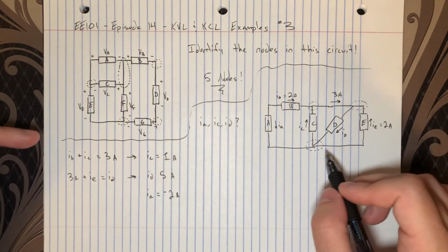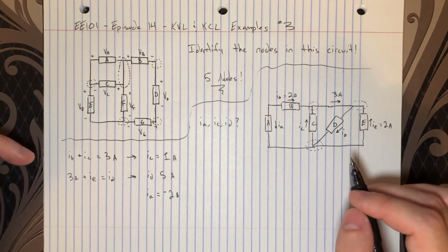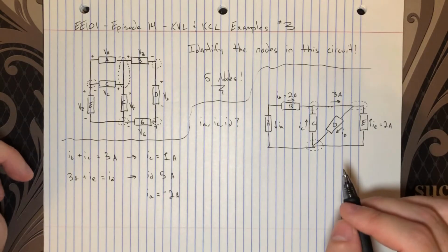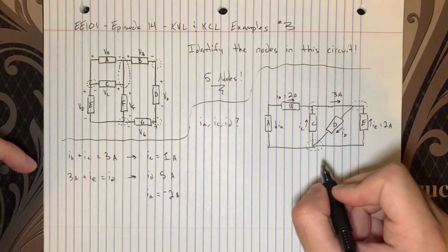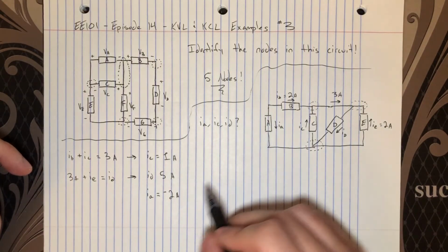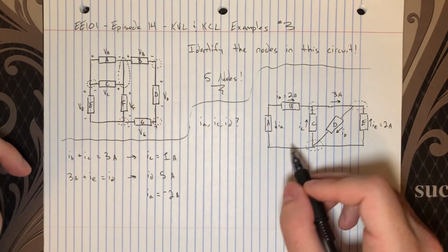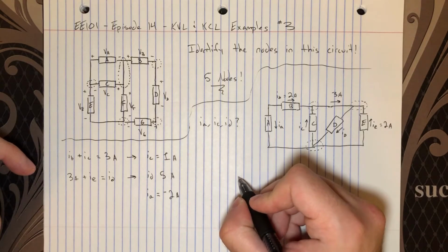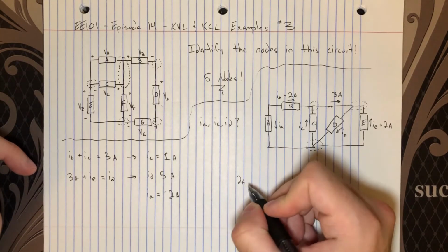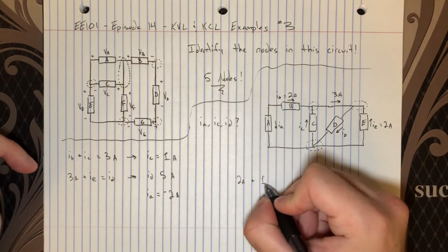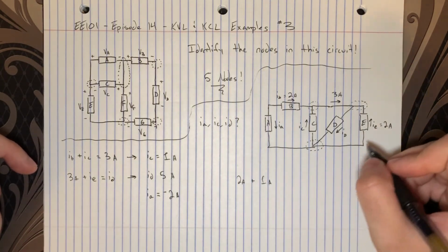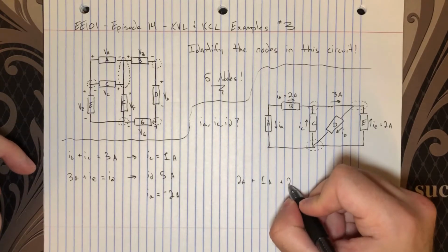So let's say that all the currents entering equal all the currents leaving. So in this case, we know that we have IA, well, we can say that because -2 is entering, we can just say that +2 leaves. So we have 2 leaving plus IC leaves, and we know IC is 1, that's 1 amp. And then IE leaves, and that's 2, so that's 2 amps.